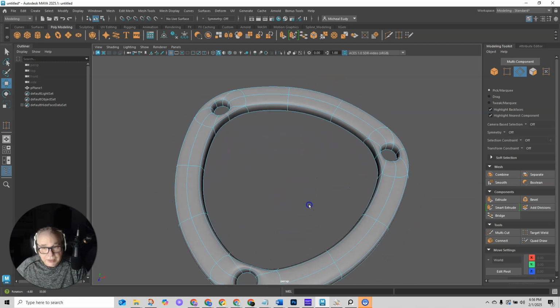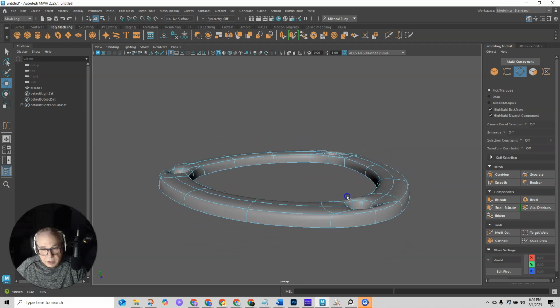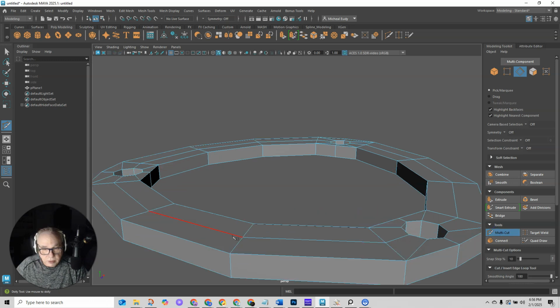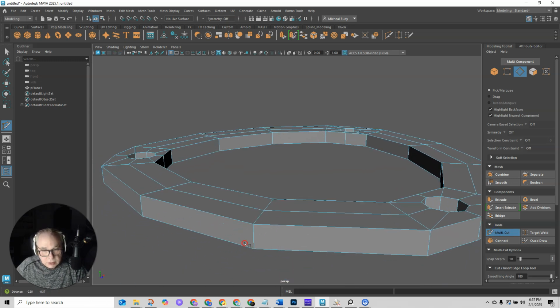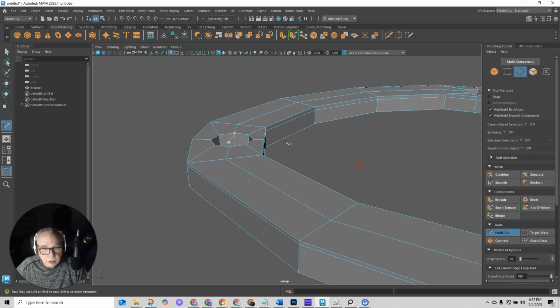We want to put some locking loops in to crisp the corners up, to crisp these edges up a little bit. So you can probably get by with just loops on the outsides if we get them pretty tight. So you want to kind of zoom in here. So Control and then the Shift and put it at 10%. And that'll get it pretty close. We need one on the inside. And then we'll need these also in here too.